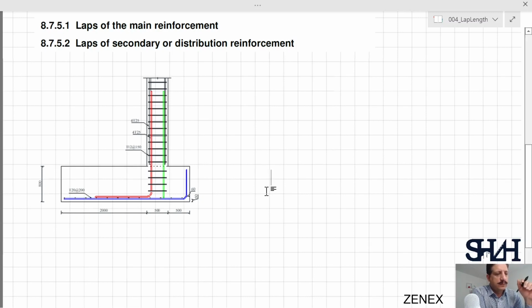As far as the bending moment usually on the column can be in both directions. For example, assume that it's coming from the wind mainly, and then the wind can blow from both sides. As a result, the reinforcement can be either in tension or compression.